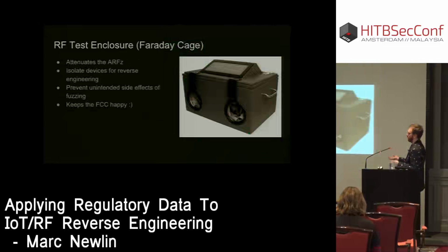This is an example RF test enclosure. This is what we use at work. These things are really fantastic because you can put your devices in there, SMA cable out to your software-defined radio, USB out to your computer. So you can interact with your SDR and your device the same way as you would out in the open, but you're protected from everything in the environment. For determining exactly what a device is doing, this is very valuable because you can know for certain that you're not looking at traffic coming from something else in the world.